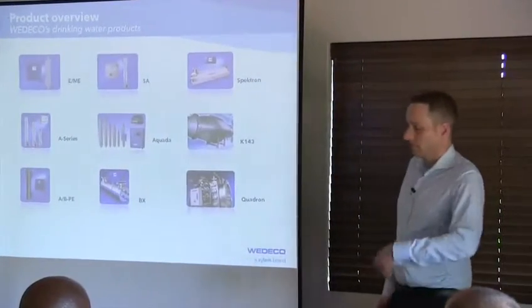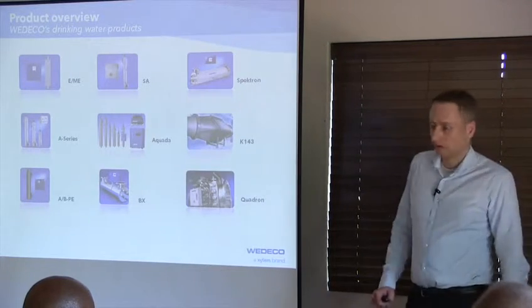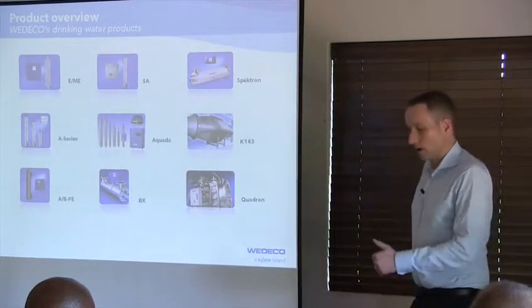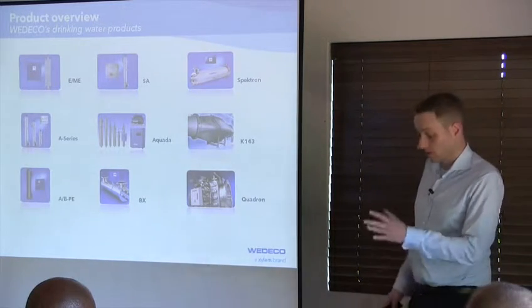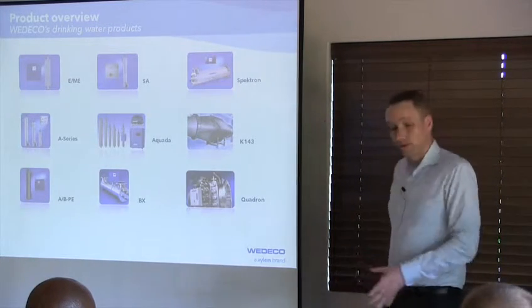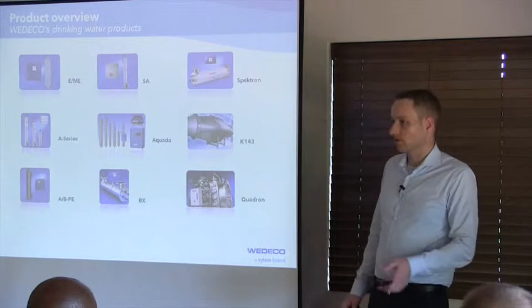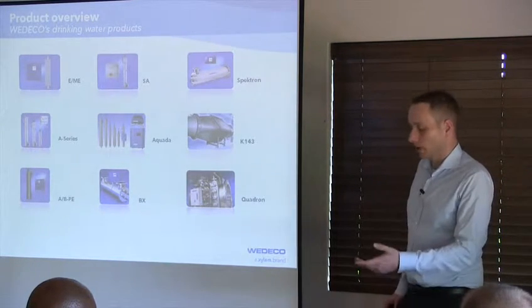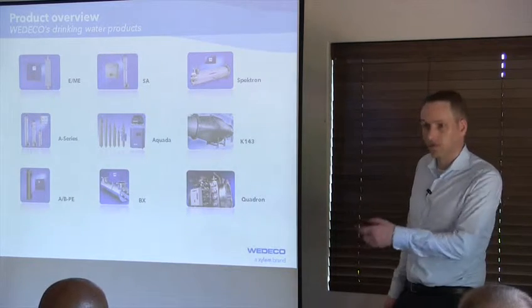If you're talking about wastewater, then for primary treatment you'd see something between 15 and maybe 30% UVT. We have sites in the UK where we do stormwater disinfection, where we have UVTs of 17%.